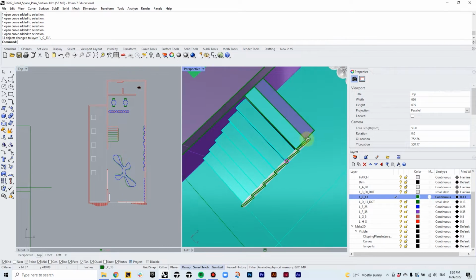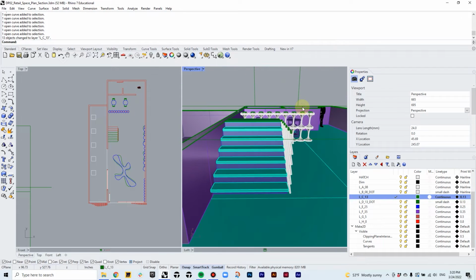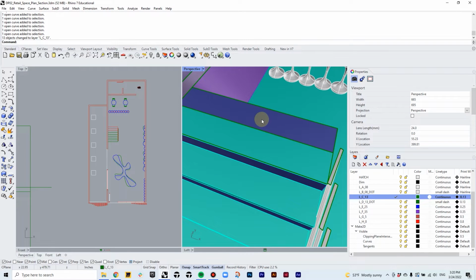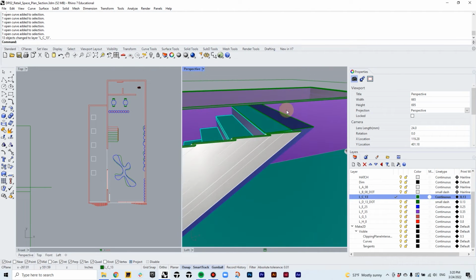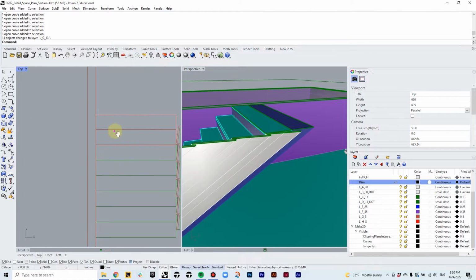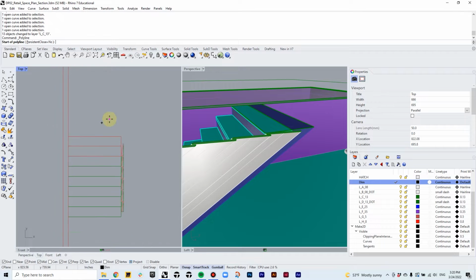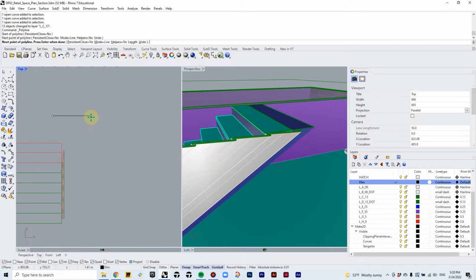And so how do we deal with the stairs? With stairs, we have a situation where the section cut is going to cut this. The way we will draw this, you can draw this on the dimension layer, is that when this section cut happens, you can start drawing a horizontal line, click, go up, and then create this kind of thunder mark.